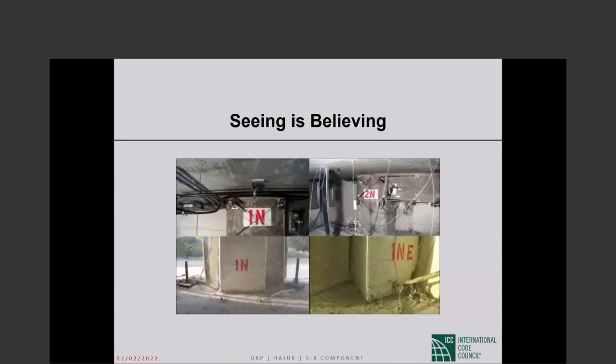The idea of the seismic weight is that it is the weight of the structure when the design earthquake hits. So if it is a storage facility, a warehouse, it is extremely unlikely that it will be entirely empty at the time of the earthquake.